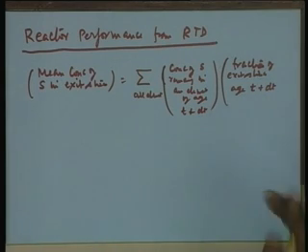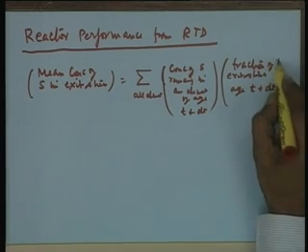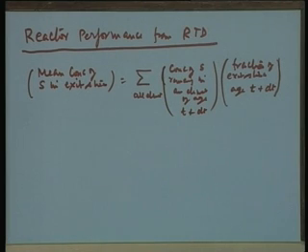Now, that means, if you take a differential element of the fluid stream which passes through in time dt, whatever the concentration of substrate in that stream is, multiplied by the fraction of the exit stream which is of age between t and t plus dt, gives the contribution, and you sum it over all the elements.